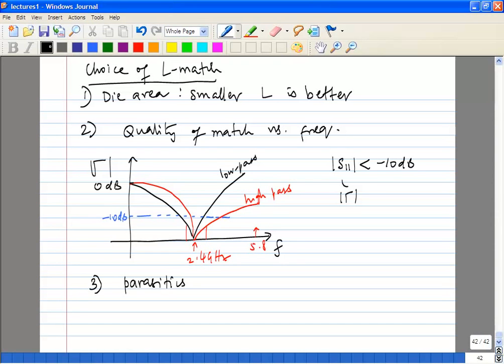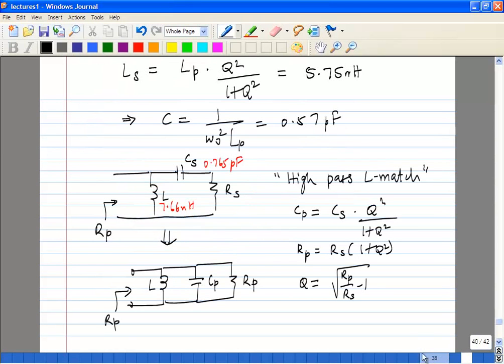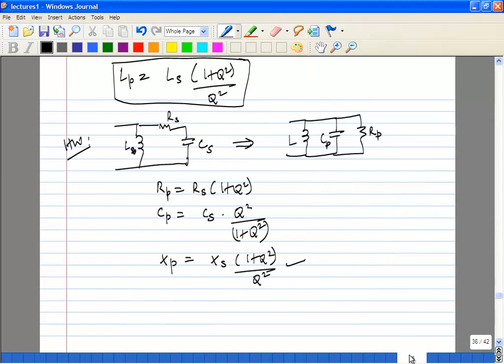So your circuit becomes more and more complicated. If you go back to the second case, if you have any series inductances before your 50 ohms, so you have L, CS, and then another series inductance that tends to cancel out your CS. What that means is if you have inductance, to get the same matching, you need a larger capacitance to compensate. So you might be better off going for the earlier match.